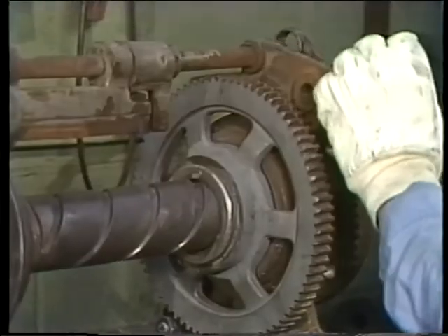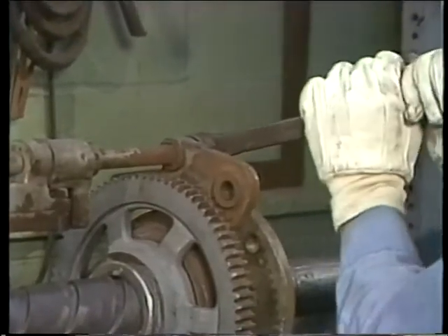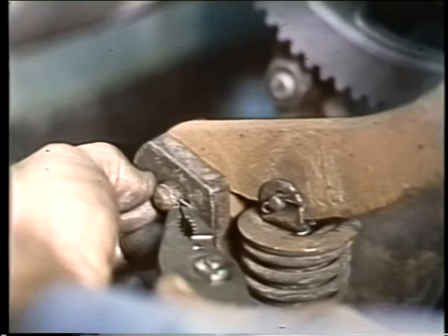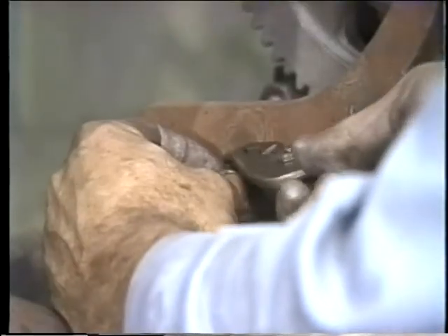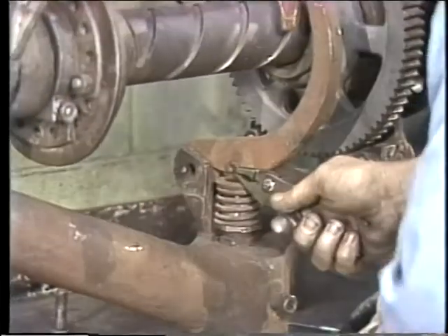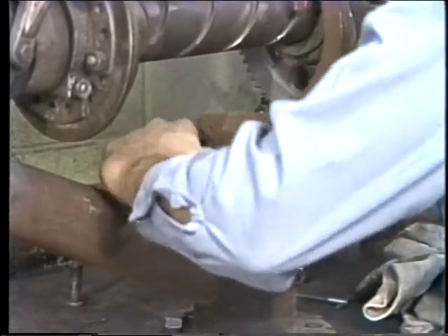When this step is completed, it's time to manually drive the element back to its fully retracted position. This will get the cam out of the way so the valve trigger can be installed. The element should travel smoothly all the way. 2 pins provide the pivot for the valve trigger. They're held in with cotter keys. Cotter keys are an expendable item. Whenever a cotter key is removed in the course of maintenance, it should always be replaced with a new cotter key. Make certain that the new cotter key is of the correct size and length.